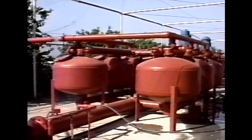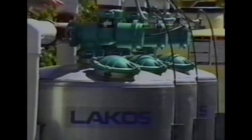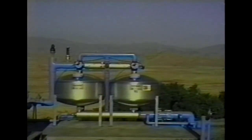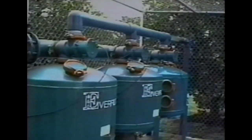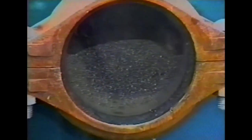Media tanks, also known as sand media filters, are pressure tanks filled with some type of sand-sized particles. They are the most popular form of filtration for drip and micro-irrigation for situations of a high dirt load of organic and/or inorganic material. The depth of the media provides a three-dimensional screening-like process that has much more debris storage capability than screens.